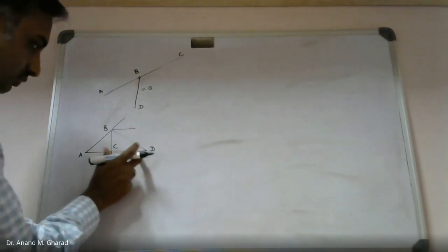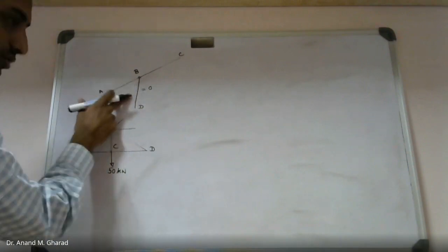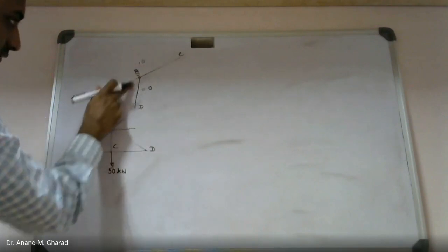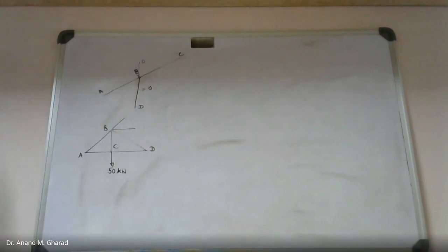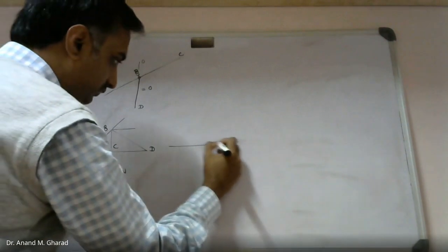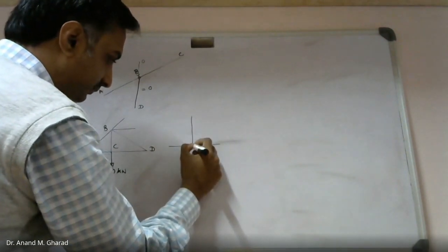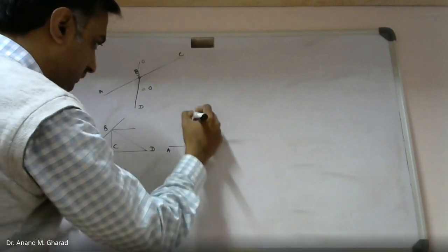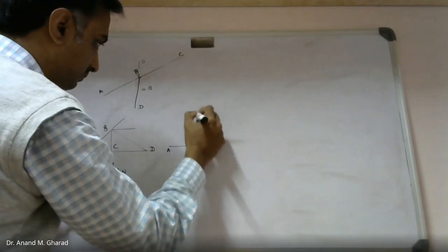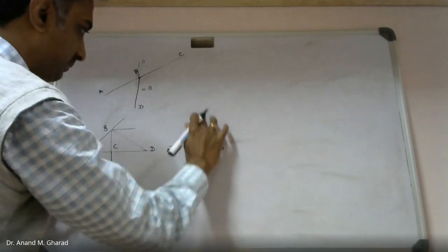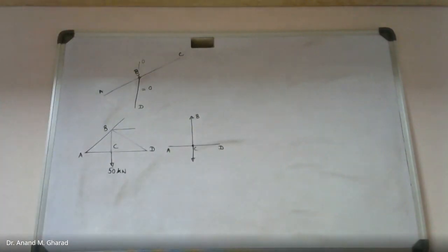So the situation is very close to this, but over here, since there was no load, zero load, therefore force in member BD is zero. If such is the situation, and now see how, if I try to draw the free body diagram associated to this, let's say this joint C, and at joint C, you have got BC member, then this CA member and CD member, like this.